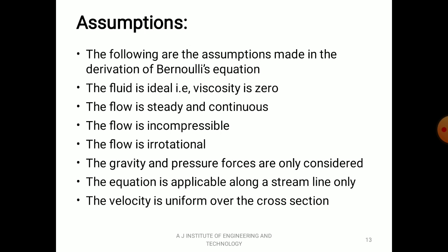The gravity and pressure forces are the only ones considered. You have seen that in the figure. There is a pressure force acting, P dA and P plus dou P by dou S into ds into dA, and there is a weight W acting, making an angle theta with respect to ds. So only pressure and gravity forces are considered. The equation is applicable along a streamline only. We derived the expression for the flow of fluid along a streamline. The velocity is uniform over the cross section, that means velocity is not going to change, it has the same value at all points.